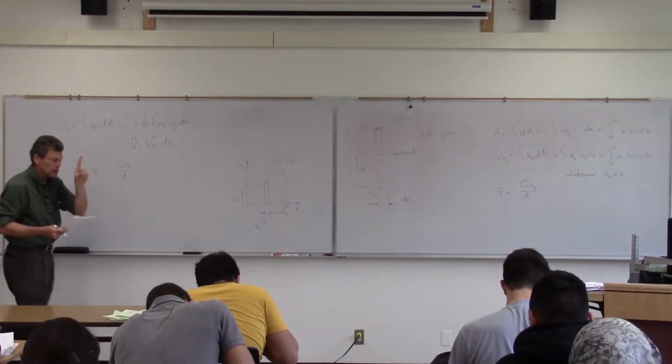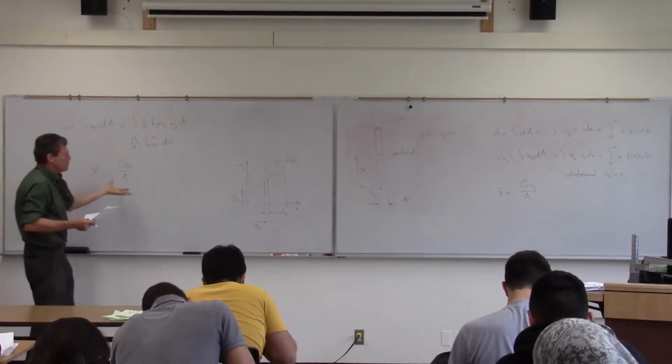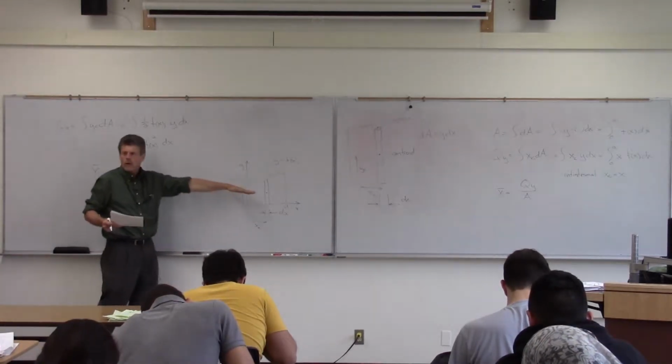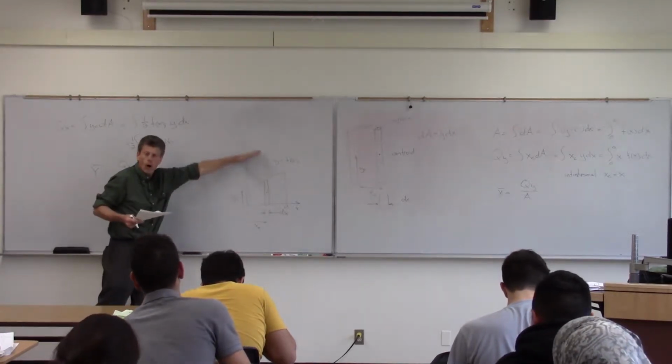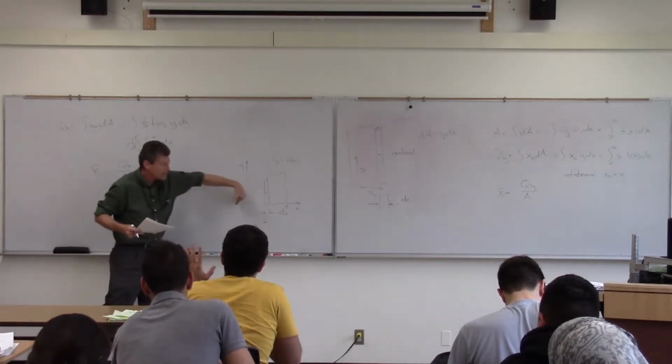So I do that calculation just once. I do those first moments of area there. That's for a vertical strip. For a horizontal strip, just the opposite. Basically, y_c will be equal to y, and your x will then be half of that function.